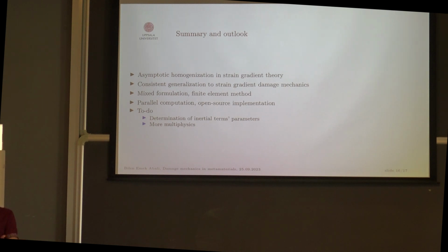I'm using a staggered scheme, because if I use a staggered scheme, then I can also use some sort of solver bound that is between 0 and 1, it's quicker. And all of these computations can be done in the finite element method by using open source implementations. So what is missing is, of course, there are a lot of numerical problems. So in order to counteract that, we are now also using Hermite and Argyris finite element methods, also IGA, but no, I'm not a big fan of it.